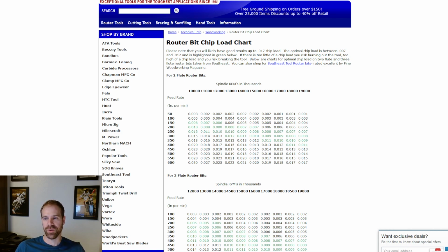I don't want to be plowing the machine through at a high rate, taking off a lot of material really fast, otherwise known as the material removal rate, and then trying to almost max out the power that the machine can deliver, because it's just not good. You can run into issues, right? Maybe you're pushing too hard and you push the plywood, or you blow a circuit breaker, or the machine literally cannot keep up. It literally does not have the power to cut fast enough. So all these things are considerations.